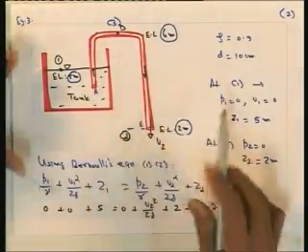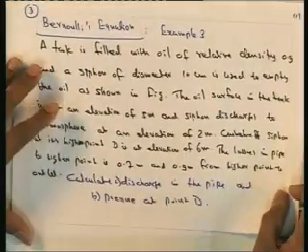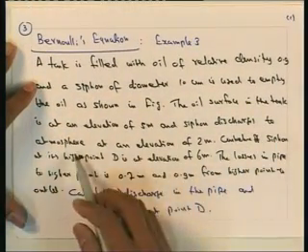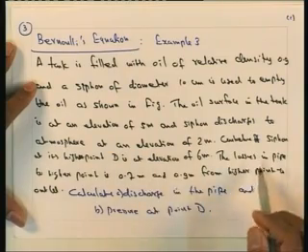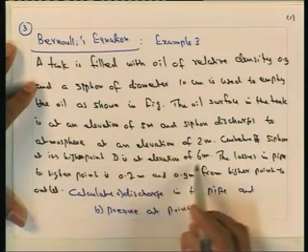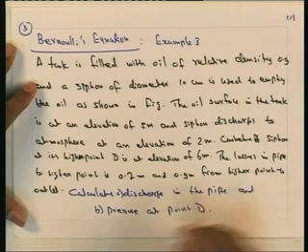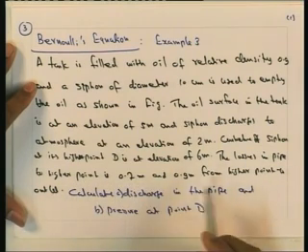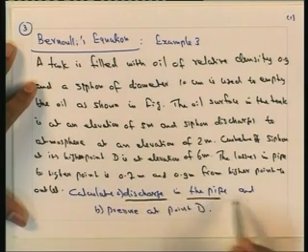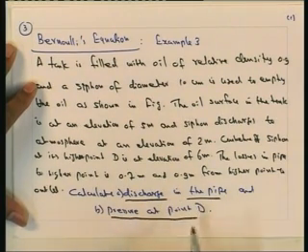like this, using a siphon. The oil surface in the tank is at an elevation of 5 meter, and the siphon discharges to atmosphere at an elevation of 2 meter. The center line of the siphon at its highest point D is at an elevation of 6 meter. The losses in the pipe to the higher point D is 0.7 meter, and 0.9 meter from the higher point to the outlet. We have to find out the discharge in the pipe and the pressure at point D.